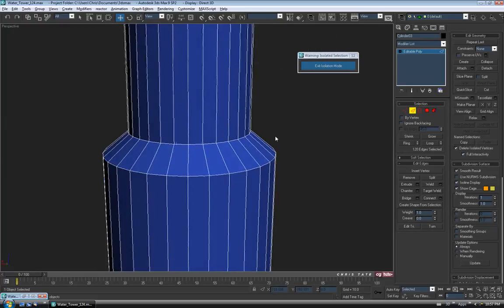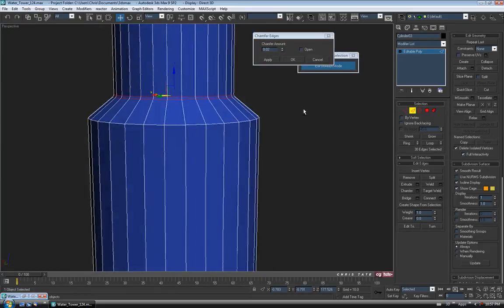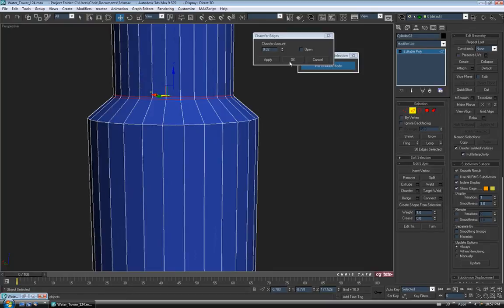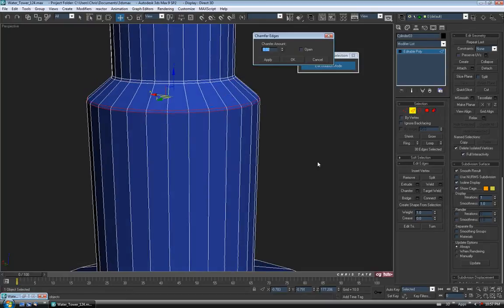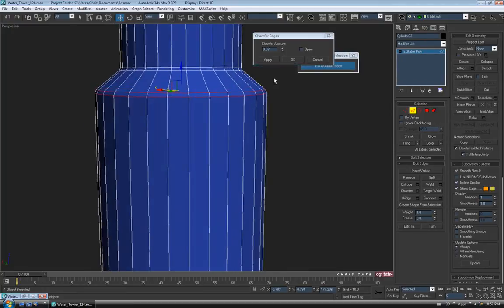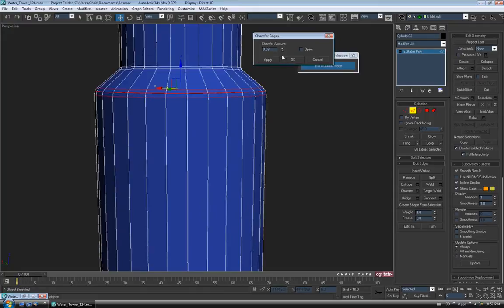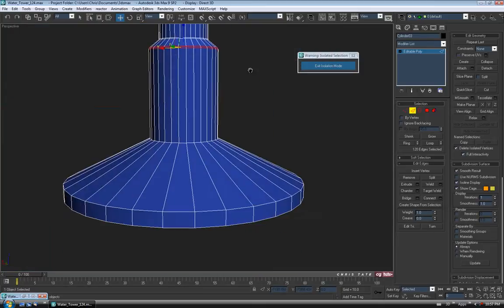And then let's move down here to the bevel detail, and we'll just grab this one, loop it, chamfer it. That might actually be fine right there, so we'll do 0.02 again. Grab the next one down, let's loop. I'm just going to take this up slightly. Maybe around 0.03, and we'll hit apply, and then lower the second amount down just a tiny bit. Let's get in here so we can actually see. So maybe take it down to 0.015 or so, and say okay.